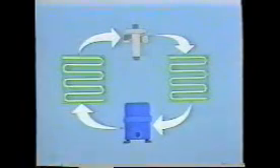This program will also cover two basic compressor designs. One kind of compressor operates by means of pistons and cylinders. As the pistons move up and down, refrigerant vapor flows in, is compressed, and is then discharged to the condenser. Another kind of compressor operates by means of a rotating impeller. Refrigerant vapor is drawn into the impeller and compressed by centrifugal force.